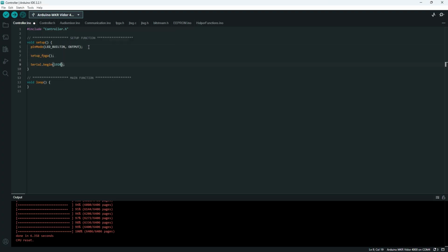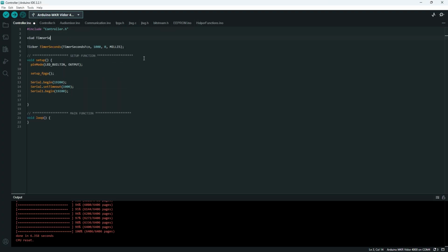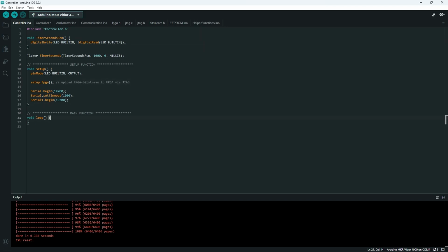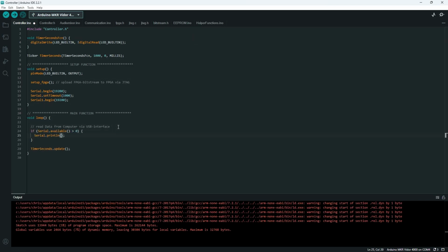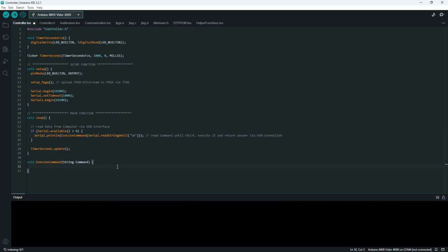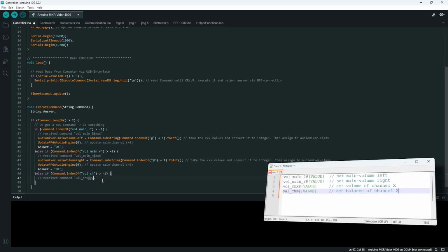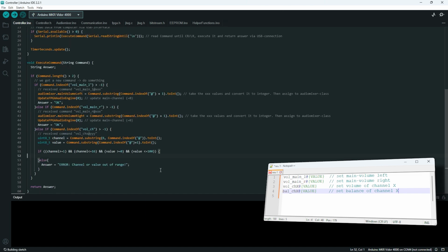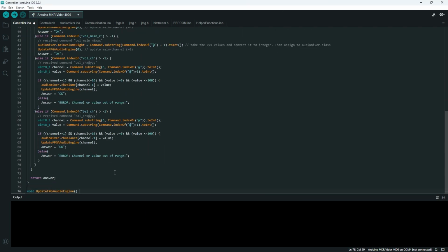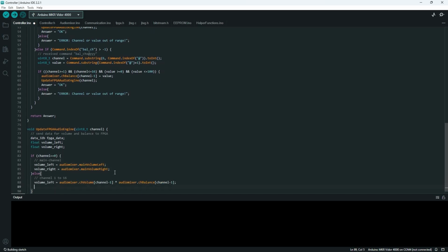On the Arduino side, we now just need to implement the counterpart for this protocol and provide another protocol to communicate with the computer. Here we simply use an ASCII-based communication so that we can easily control our new audio mixer via a terminal. After initializing the 2 serial ports, we can test our system now.